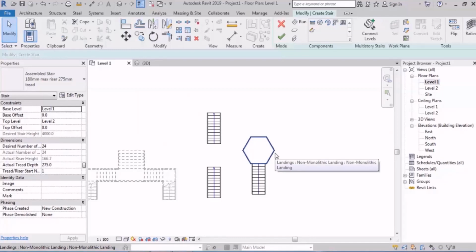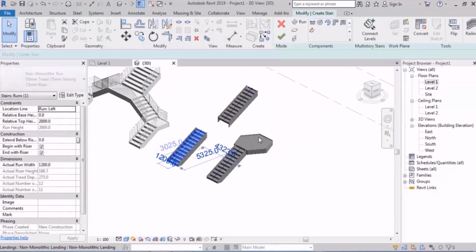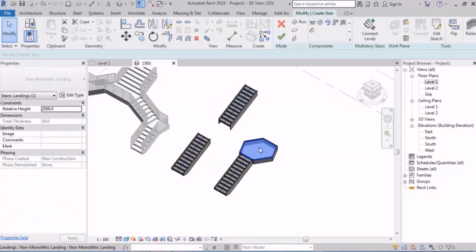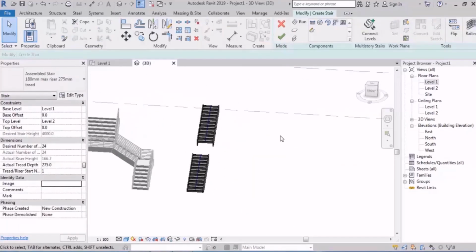Also remember that while you're drawing your stairs, they must never have the base offset. Well, of course, the stairs of the first ramp. The second ramp starts from a different height. But generally, the stairs must not have a base offset. So, if we draw the landing separated, which I said is useless, we need to adjust the height again.